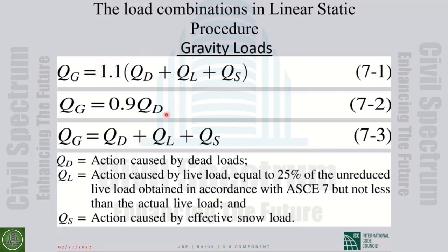So usually codes have a smaller value of the gravity load proposed for the anchors, elements that, due to uplift, for example, if increasing the lateral load, vertical load will reduce their design values. It's not good. So in fact, we have more or less two main gravity combinations.